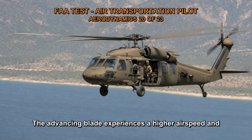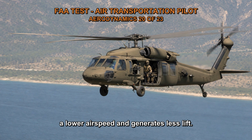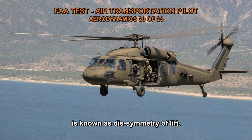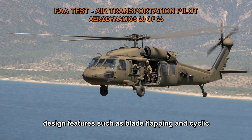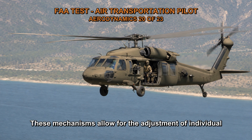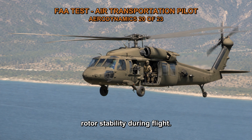The advancing blade experiences a higher airspeed and generates more lift, while the retreating blade experiences a lower airspeed and generates less lift. This difference in lift production between the blades is known as dissymmetry of lift. To compensate for dissymmetry of lift, helicopters incorporate design features such as blade flapping and cyclic control inputs. These mechanisms allow for the adjustment of individual blade pitch angles to equalize lift and maintain rotor stability during flight.